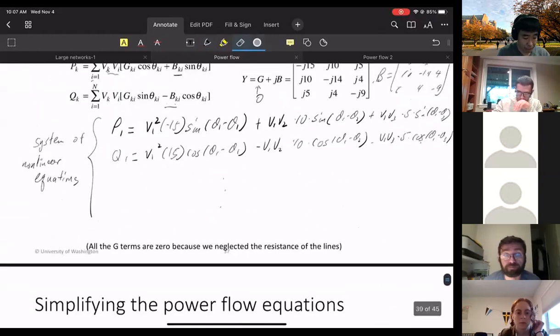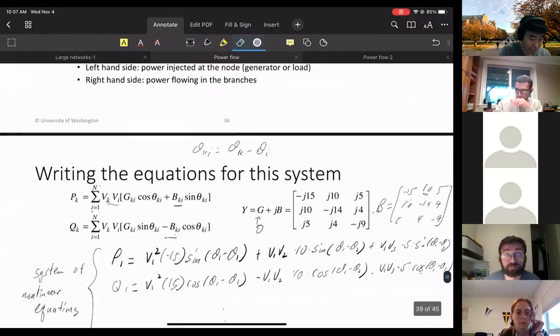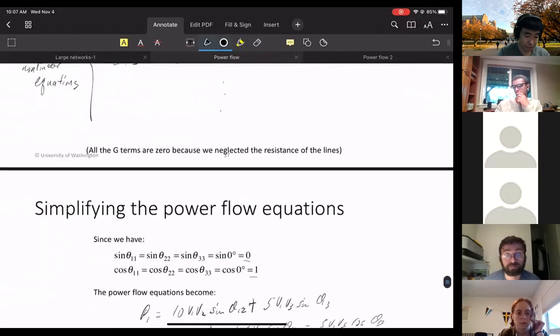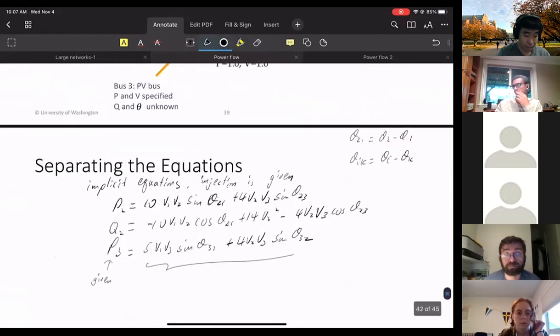So if you look at the summation equation, for example, from bus k, we're fixing k, right? So we're fixing the first index, and then we're changing the second index on the angles. Meaning we're looking at a bus, the power flow out of this bus to the other buses. Okay. Yeah, so this is notation, right? So we always think about the power flowing out of the bus, even if it's a load bus, right? So theta 2 1 is probably negative because it's consuming some power. But anyways, that's an equation we'll write this way, okay, for consistency. Good. Any other questions with this?